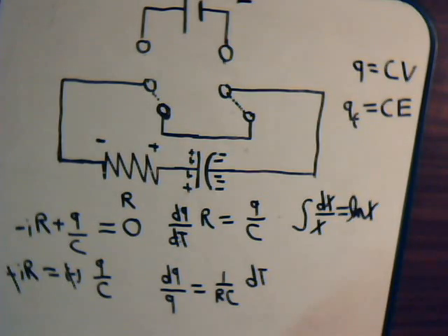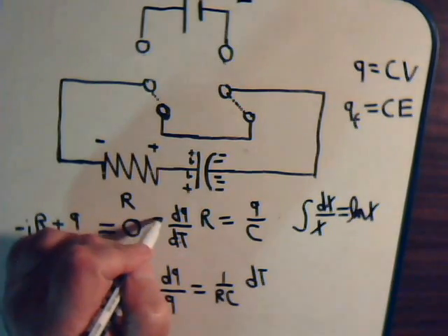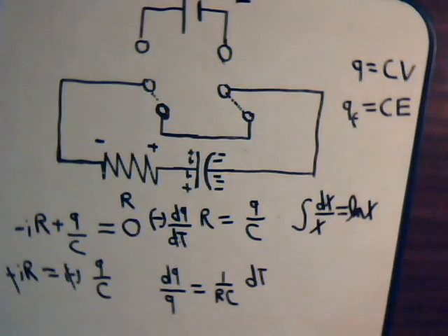So that means that dq/dt is going to be getting smaller over time. So dq/dt is really a negative quantity. And again, the reason is the charge decreases over time, so its rate of decrease is not going to be a positive number. It's going to be a negative number. So let's put the minus sign over here.